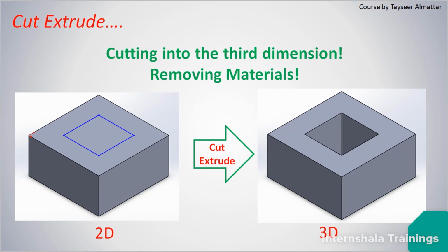Cut extrude is the opposite of extrude boss. Here we are cutting into the third dimension by removing material. With cut extrude, we can go from the 2D sketch on the left to that hole you see on the right.